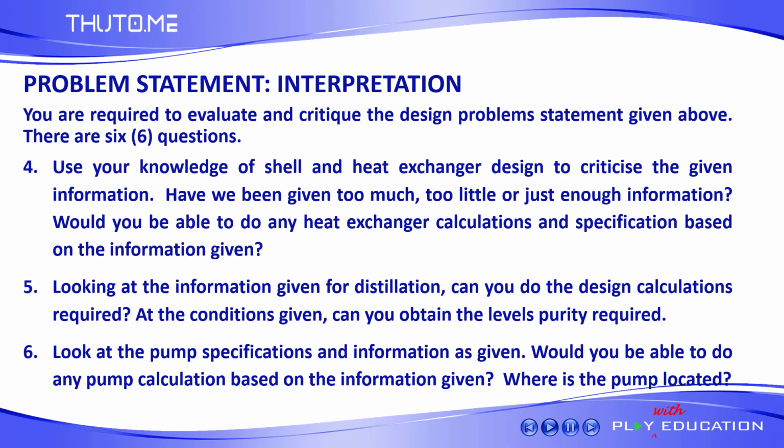The fourth question focuses on the shell and tube heat exchanger specifications. You have been given the flow rate, the inlet temperature, and the outlet temperature. Also, you have been given the inlet temperature and outlet temperature of the heating medium. The heating medium is not specified. Is it steam? Is it hot oil? We don't know. The heating stream flow rate is not given. We have been told that the heating medium is on the shell side of the heat exchanger.